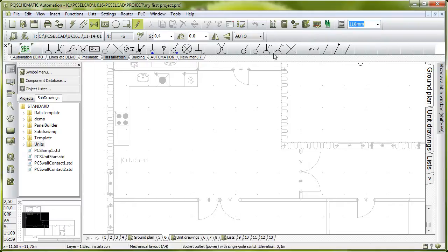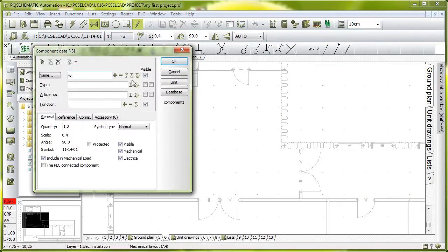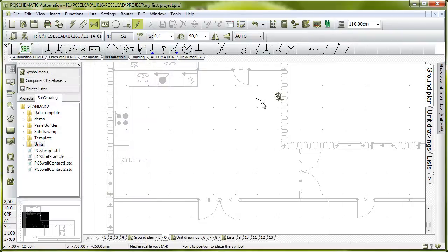Or I could go in and select it from the pick menu, where I have placed a couple of symbols in the correct elevation. So if I want it to be placed at 1.1 meter, I'll simply select this one and then I'll place it where I want it to be. I can hold down the shift button to put it tighter to the wall here, and then I can simply place it, give it a name, and keep the name invisible, because I don't think that you want to see the name on the drawing here, but later on you'll want it.